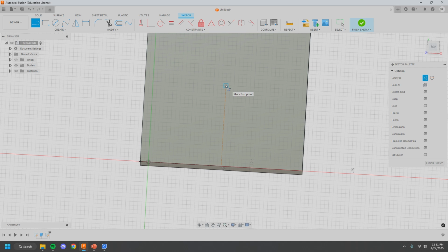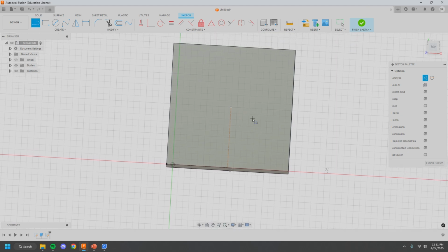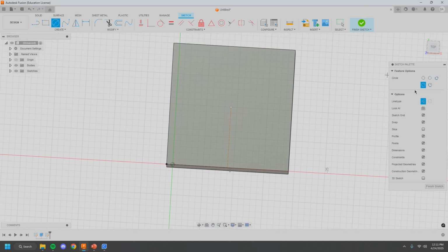So for example, I got to the middle of my box there to place this circle by just doing one line here, going to the middle, and one line up from that middle to the very middle point of the box. And so I'm going to now click on create a circle. I'm going to unhighlight construction line, and you'll see here what this allows me to do is now click on that middle point that I just made. That's why you want to use construction lines.